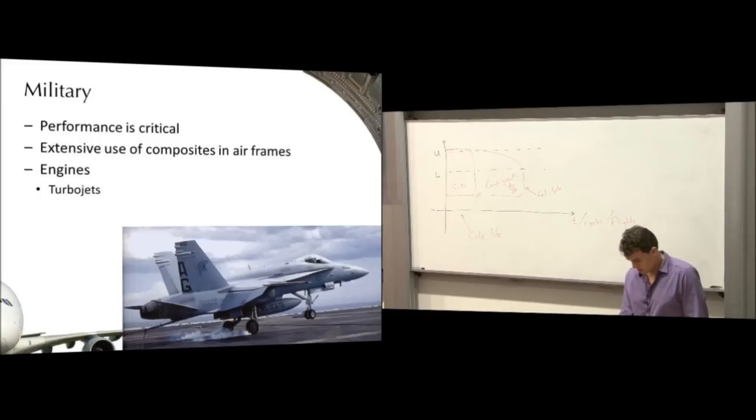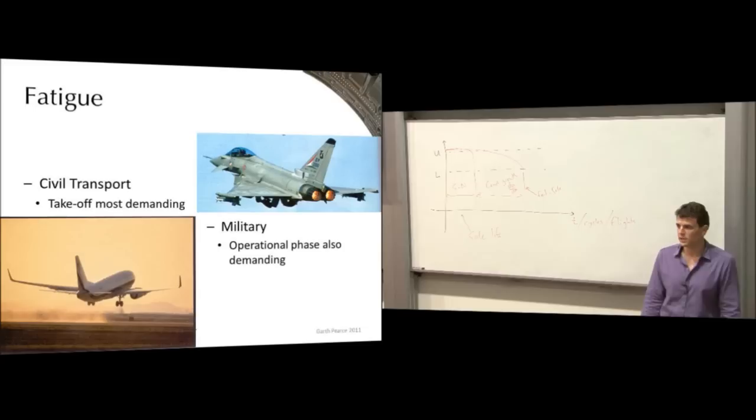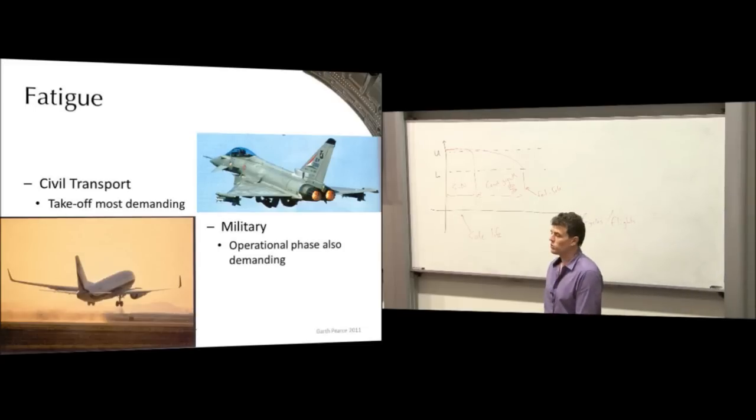Okay. We also have to think about where the sources of fatigue come from. With civil transport, it tends to be takeoff and landing, or takeoff generally, where most of the fatigue occurs. If you think about an aircraft throughout its flight cycle, it's fully laden at the beginning, but by the end it might be 30% lighter because it's burnt all its fuel. So the loads when it takes off are generally higher than loads when it lands. Also, the act of climbing means you have to apply a higher load than when you're cruising, because one's accelerating and one's straight and level.